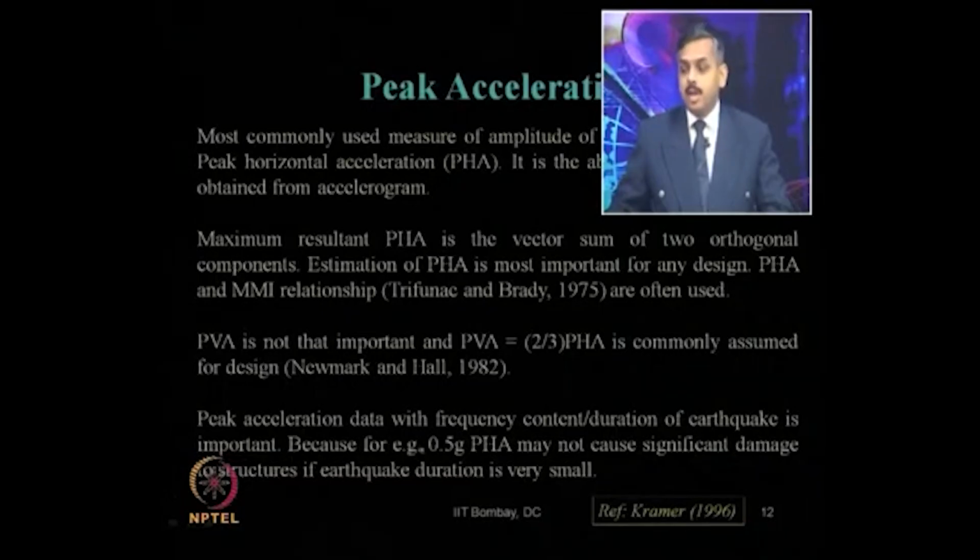Peak acceleration data with frequency content and duration of the earthquake is important. That is what we mentioned in the previous lecture, and the reason is also given here. For example, 0.5 g of PHA may not cause significant damage to a structure if the earthquake duration is very small.